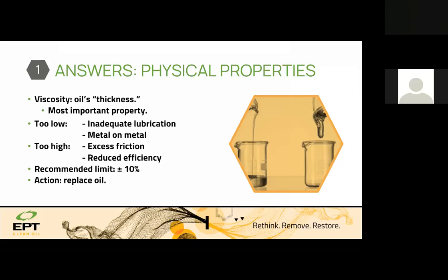But whenever you have an immediate change in viscosity, a decrease or an increase, you need to check if a wrong lubricant was added to the system. But if the lubricant is aged and has a long life, you need to check for the end of life of the lubricant and oxidation.